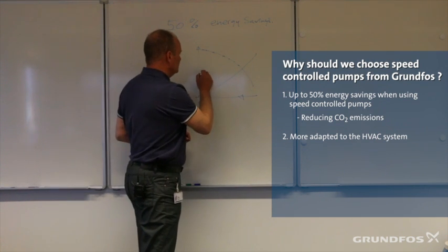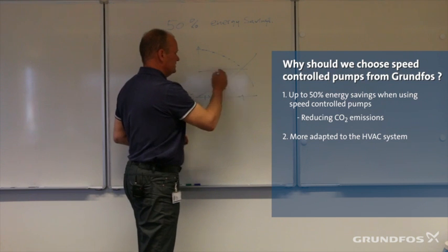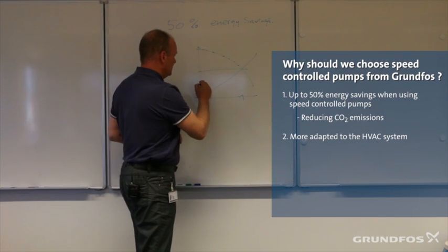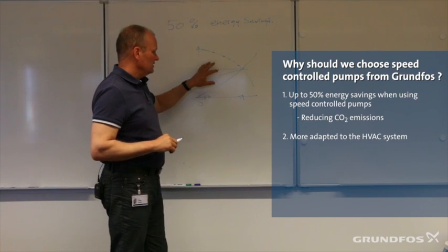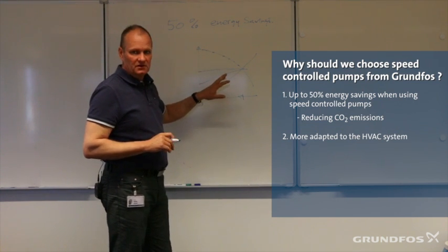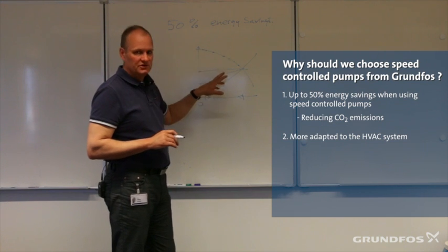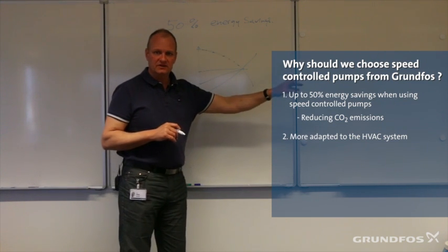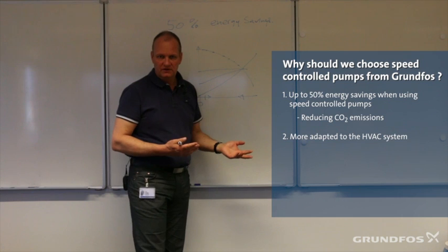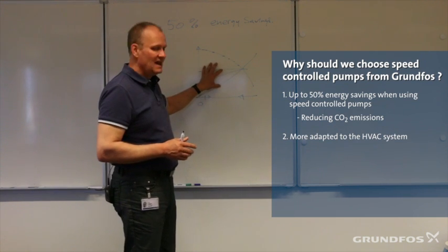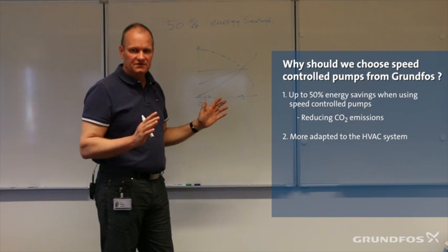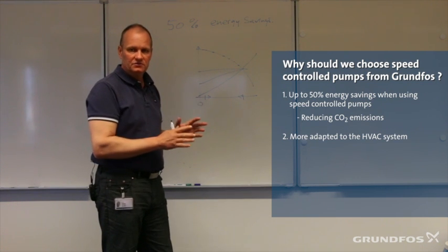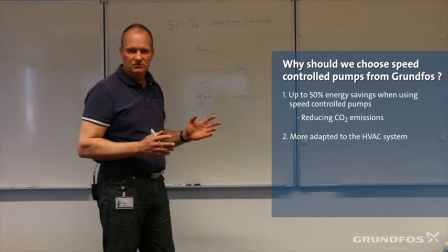So what we do when we have the E-Solutions is that we choose the optimum control strategy, either constant pressure, proportional pressure, or proportional pressure measured out in the system, as we have already discussed. So having pumps which perfectly match the overall HVAC system is another huge benefit when we're talking about E-Solutions from Grundfos.